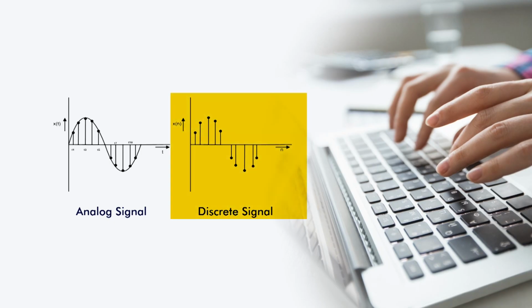The right hand side figure which is shown on your screen is the discrete signal. As you see in the figure, a discrete time signal has a value specified only at discrete points in time. Here at definite time intervals, we can say it is 10 milliseconds or 10 microseconds or half an hour, the signal value is measured or observed. Our interest is to know the magnitude of the measured or observed values at specified intervals of time, then it is a discrete signal. And how is it obtained? It is obtained by sampling continuous time signals.